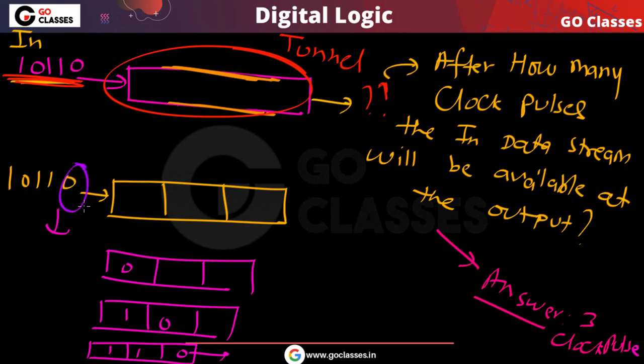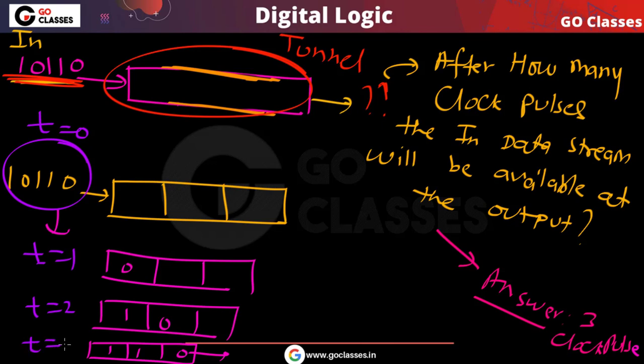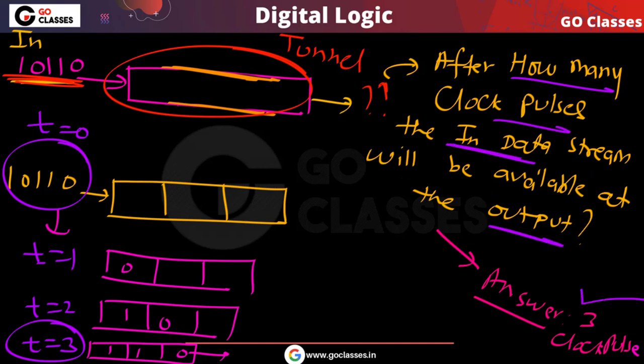Now you can notice this 0, we inserted this. Let's assume this is time t equal to 0, this is t equal to 1, this is t equal to 2, and this is t equal to 3. At time t equal to 3, the data that you inserted is available at the end. So after 3 clock pulses the input data stream will be available on the output.